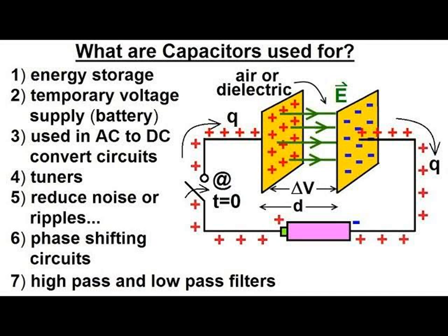The amount of electrical energy stored in a capacitor is dependent on the potential difference applied in the capacitor. In other words, the work done in charging the capacitor is directly proportional to the potential difference passed through the capacitor. So work done is directly proportional to VQ. And then you know that V is equal to Q all over C. So substitute your V to be Q all over C, then integrate Q all over C dQ. And when you do that, you will end up having Q squared all over 2C.